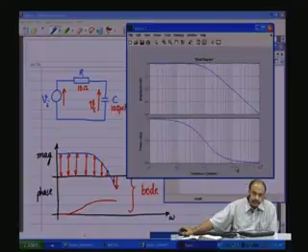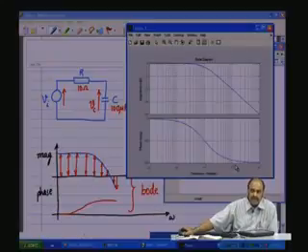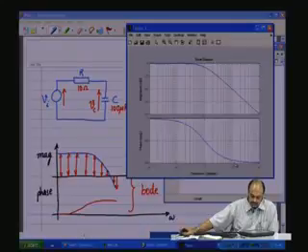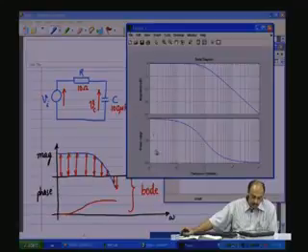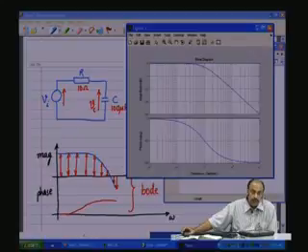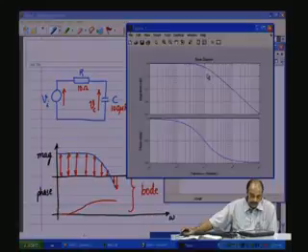This means that at very high frequencies, when it is truly behaving more like a capacitance and the resistance is swamped out, it is a capacitive load, and therefore, you have a 90 degrees phase shift. So, this is the meaning. Therefore, both the magnitude and the phase are important when you have to discuss the response of the circuit to any input waveforms in the frequency domain. This is the Bode diagram or the Bode plot.